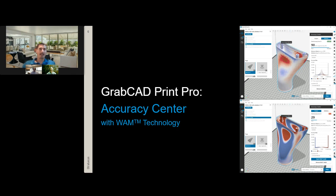And what I think is the coolest part of this module is actually what we call the WAM, the Warp Adapted Model technology. And so based off of this histogram and this accuracy score that we have, we can actually pre-warp the STL file based off of the comparison to greatly improve the accuracy of the next part. So as long as you're holding all things constant, you're building the part with the same material on the same machine in the same spot, we can see a great improvement in the accuracy of the part.